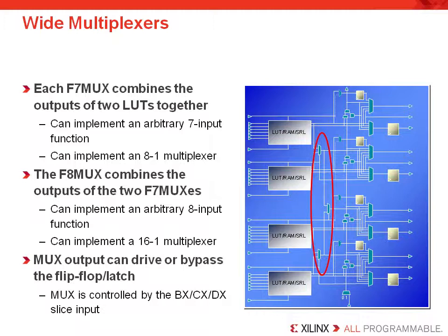These dedicated multiplexers are used to improve the speed of large multiplexers and save LUTs for other purposes. The reason that these multiplexers improve the speed of the design is because there is dedicated routing between the multiplexers that are low fan-out and fixed between the logic resources. It is also fast because the dedicated multiplexers are faster than building the equivalent logic just with LUTs.